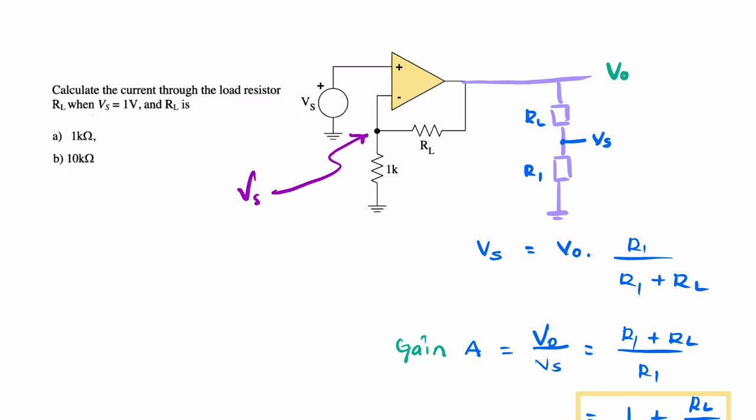So if I put that back, we can now look at the diagram as it is. You divide this potential divided by this resistance. So it really doesn't matter what the feedback resistance is. It's independent of the feedback resistance.